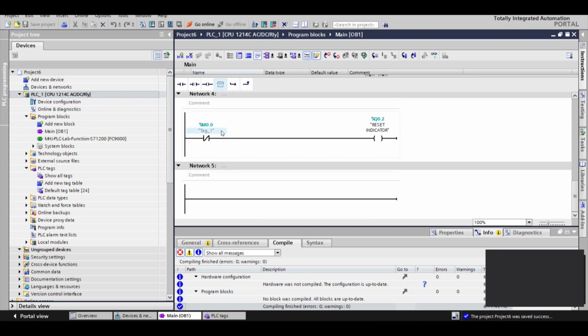Sometimes it depends on the model of the PLC. Sometimes it requires a password. But do remember the password because when downloading it, it will ask. So if it has given a password error, there will be two places where you need to enter the password. So try to compile it again and then it will specify exactly where to enter the other password.